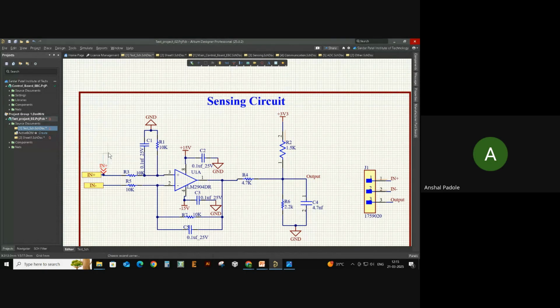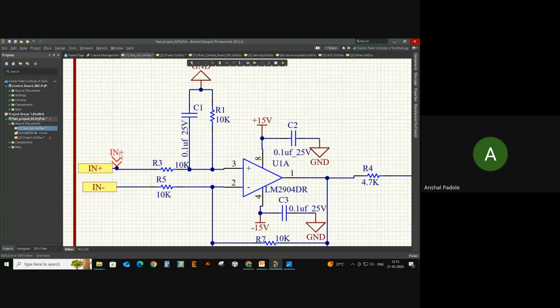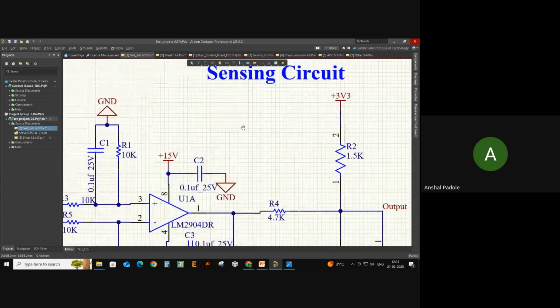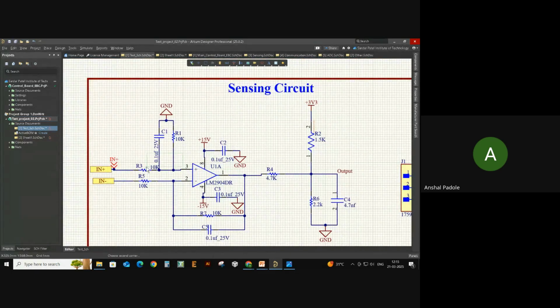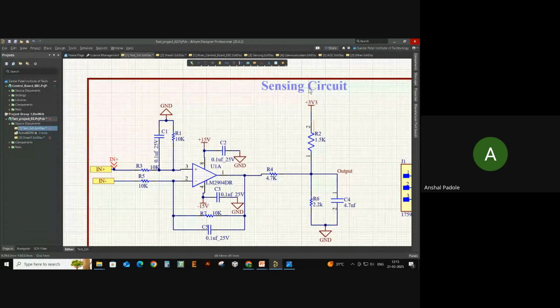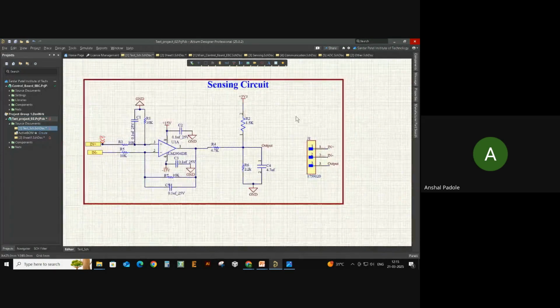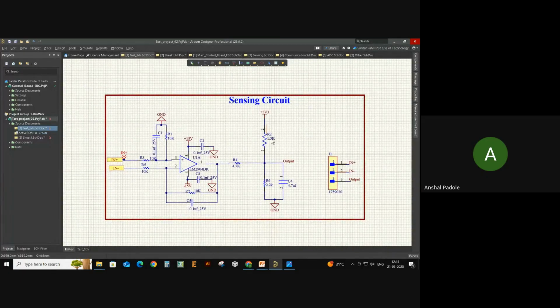It won't allow me to change the ports as well. You can see over here, whenever I select the port and try to change anything, it won't happen. That is basically one use of the selection filter. If I want only text to be selected and nothing else, I can just select the text, and nothing will happen to my original schematic. Only the text which I have made is editable right now. This selection filter also helps very much when there are so many things on the schematic.